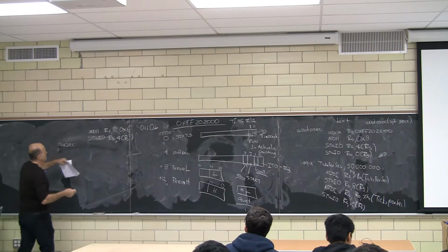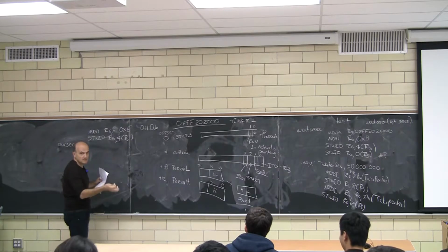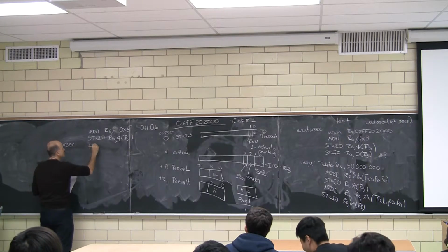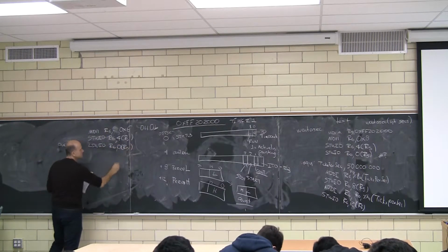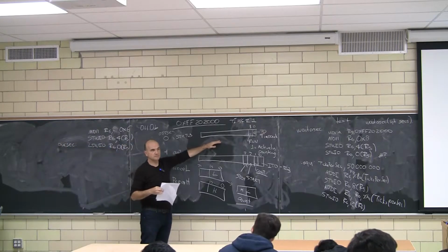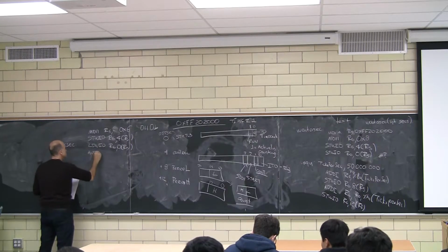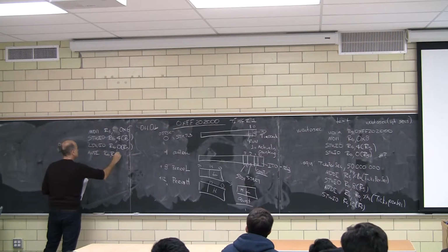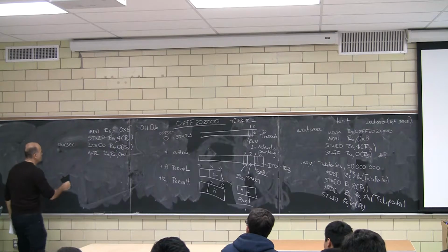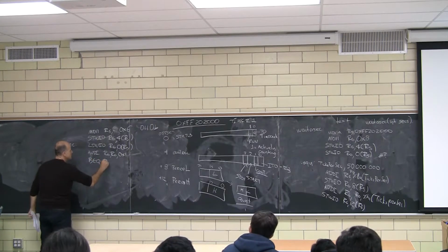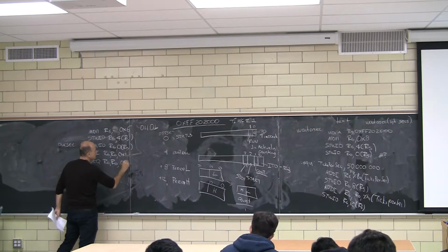We're good? Okay. So from this point on, we're going to be reading the status register and asking, did you time out? That's the thing. So we're going to say load word IO R6, 0(R5). We're getting all the bits here, and we need to keep just the last one. So we mask out all but the last bit. And then, as long as it hasn't timed out, so as long as this result is 0, it means that it is not set yet, so wait.